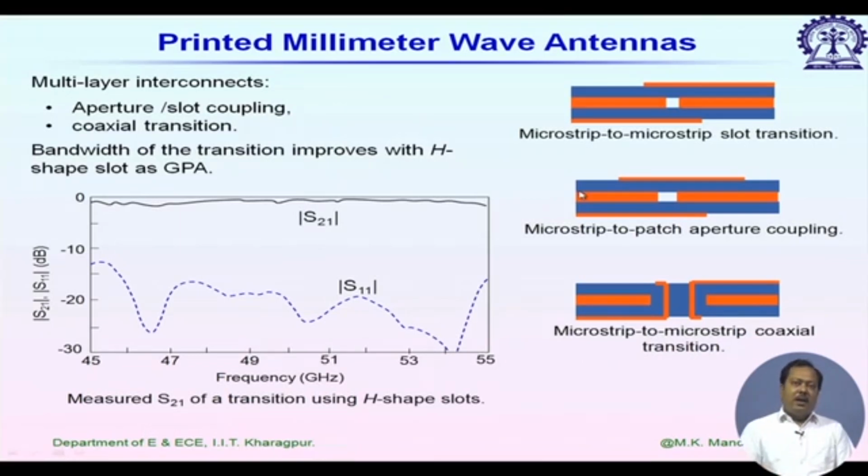Now, when we design at millimeter wave frequencies, we have seen that we have to use a thinner substrate. People typically use 10 mil or 5 mil substrate for 60 gigahertz application. Since the substrate thickness is very small, it is fragile and not mechanically rigid. We have to use some supporting structure. Usually people use a brass plate with that. Then how to design the transition through the brass plate from feed network to patch antenna becomes another challenge.